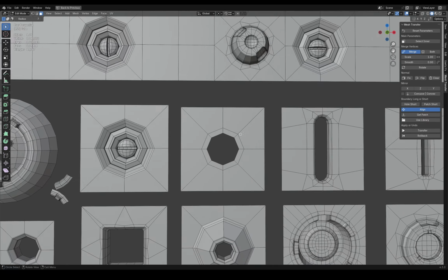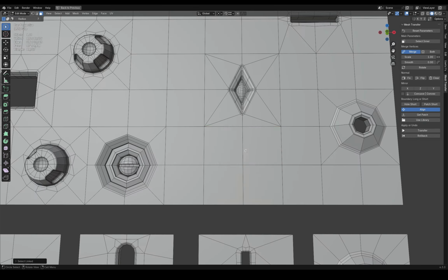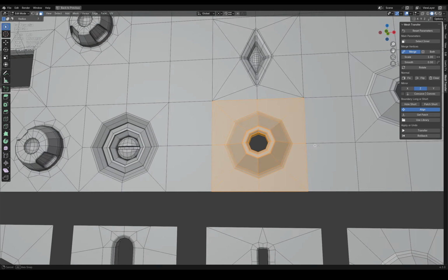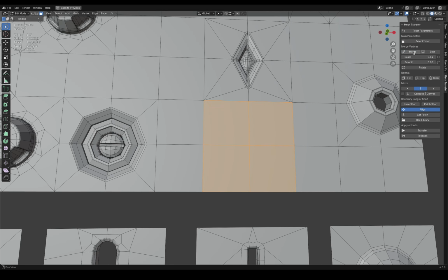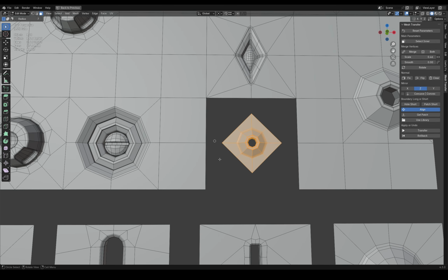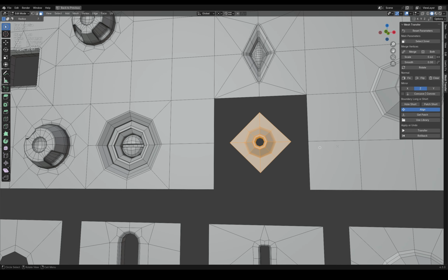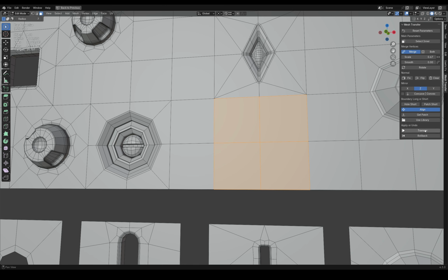Now I will get data about the new mesh that I want to place on another mesh. At the moment the mesh has moved upside down. To fix this, you need to use the mirror parameter. We can also change the scale of the mesh, but I do not advise you to use too low or too high values, as this can lead to incorrect stitching of the patch vertices with the main mesh. But this parameter can help you adjust the scale in some cases so that the mesh fits more correctly.